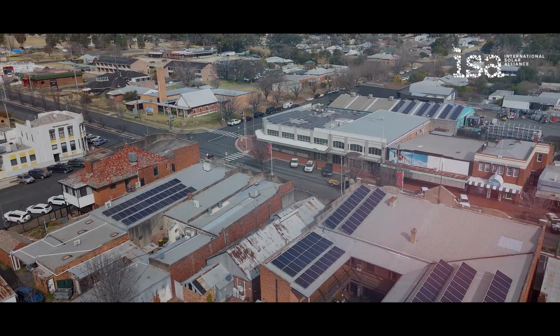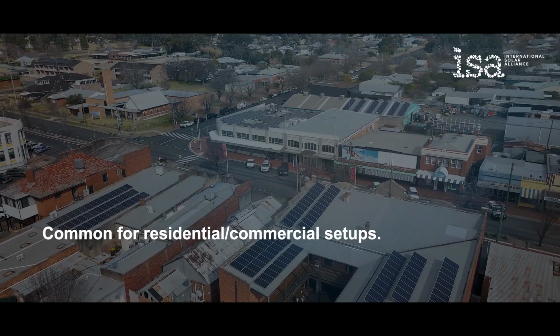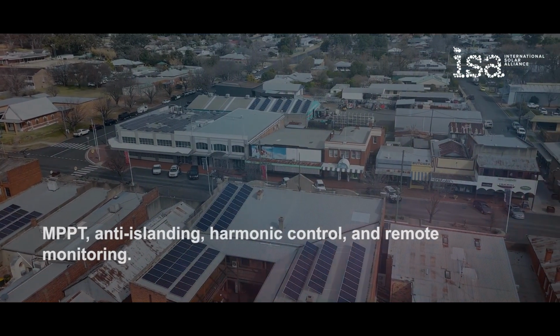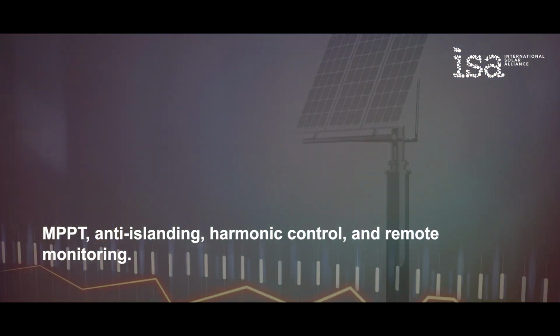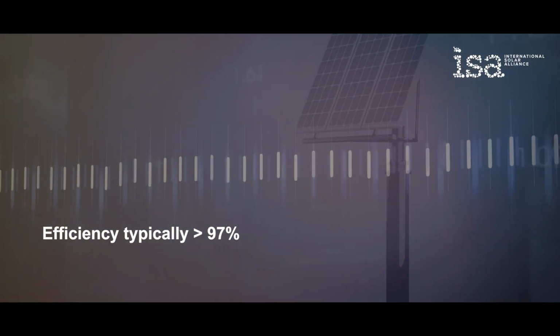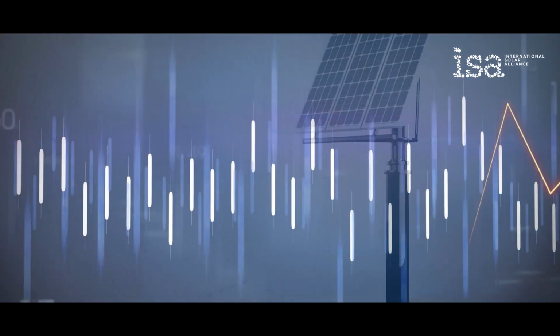Common for residential and commercial setups, they directly feed AC to the grid with real-time synchronization. They feature MPPT, anti-islanding, harmonic control, and remote monitoring. Efficiency is typically greater than 97%, with automatic restart when the grid returns.